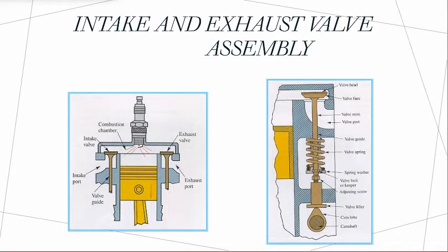Valve may be positioned vertically or slightly inclined relative to the cylinder axis, matching the desired combustion chamber contour. Poppet valves have different configurations within the engine relative to the cylinder. In the overhead cam engine, the camshaft is mounted in the head either above or to one side of the valve, which improves valve action at higher engine speed. The valve is operated directly by means of valve lifters or cam followers or through rocker arms.